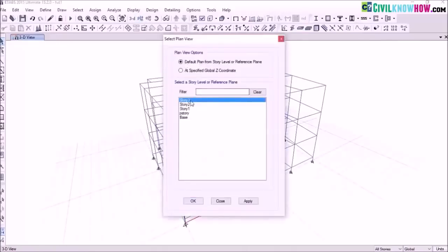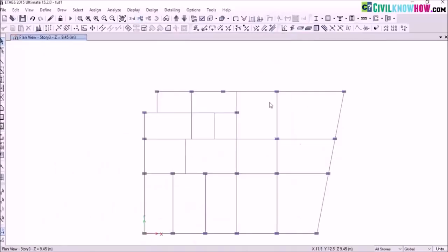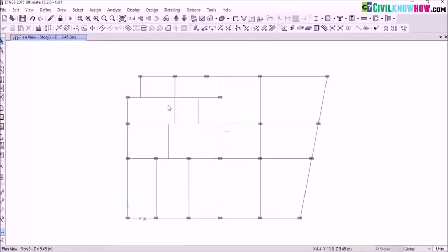And let's go to the plan view. But in my actual plan, the orientation of my columns are not in a single direction, because some of my columns are in orientation with respect to 90 axis, and the columns over here are in orientation with an angle actually. So let me first select the columns that I need to orient to the 90 degrees.